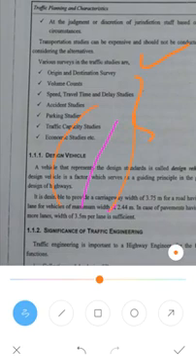So these are the different types of studies: origin and destination survey, volume counts, speed, travel time, accidental studies, parking studies, traffic capacity studies, and economical studies. Among all these factors, the most important for deciding the types of roads, whether service road, national highway or state highway, are the speed, travel time and delay studies, and the traffic capacity studies. These are the two important factors for deciding the type of road for a particular location.